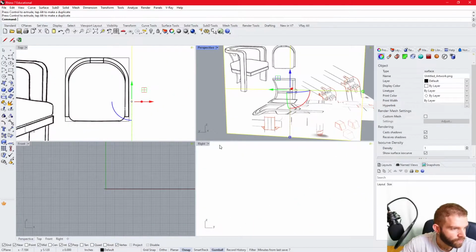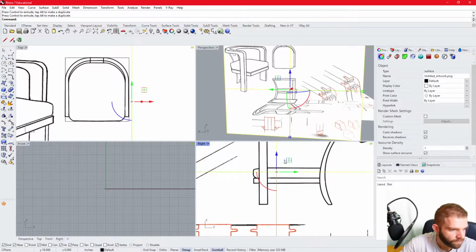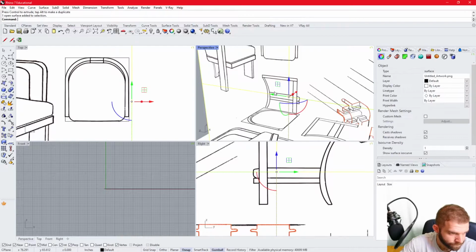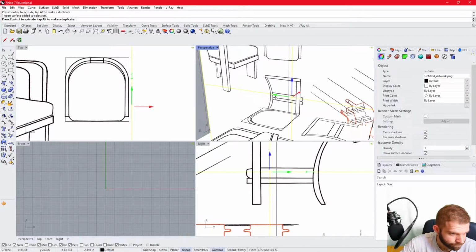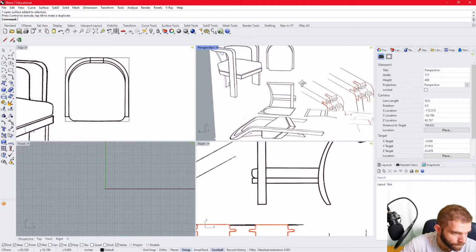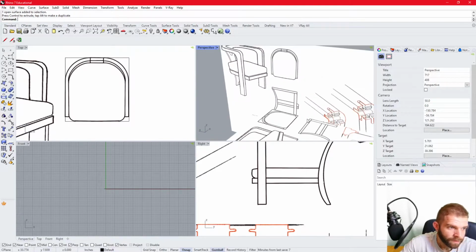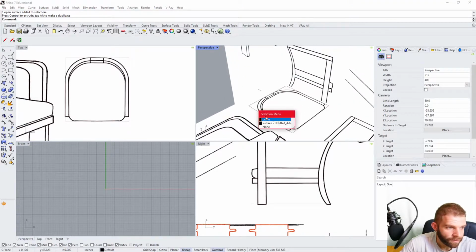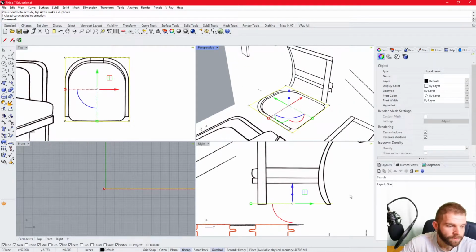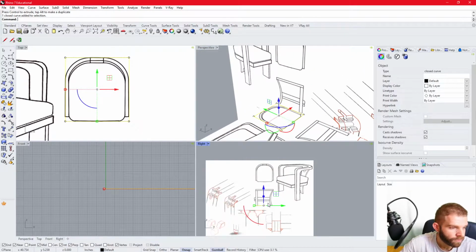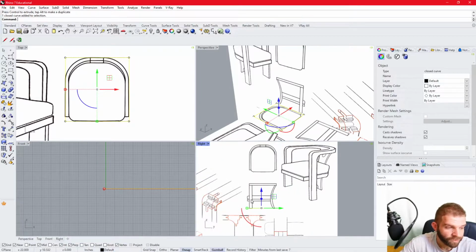I can always go into a side view. And there we are. It's rough, but it's good enough. So this way I can now copy the rectangle to set the height constraint. Now, I could Control-C, Control-V, right, or copy paste. Instead, I'm going to use the copy command.